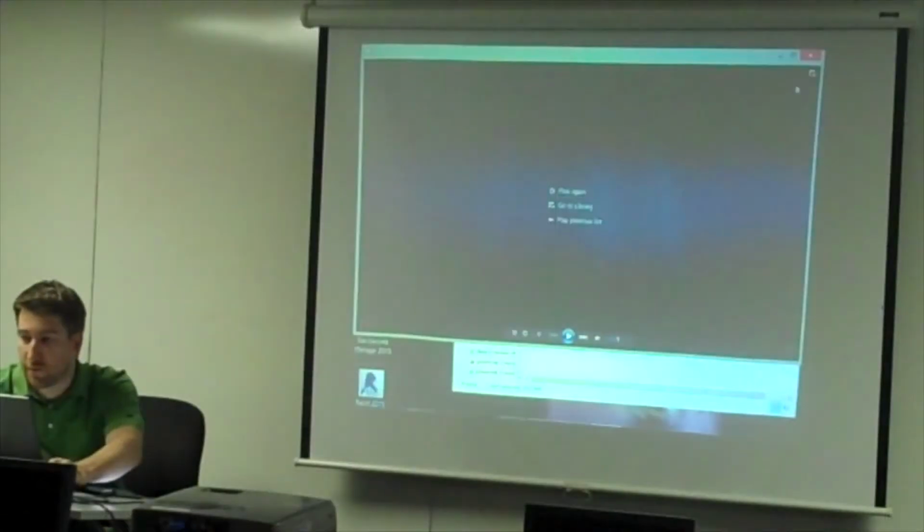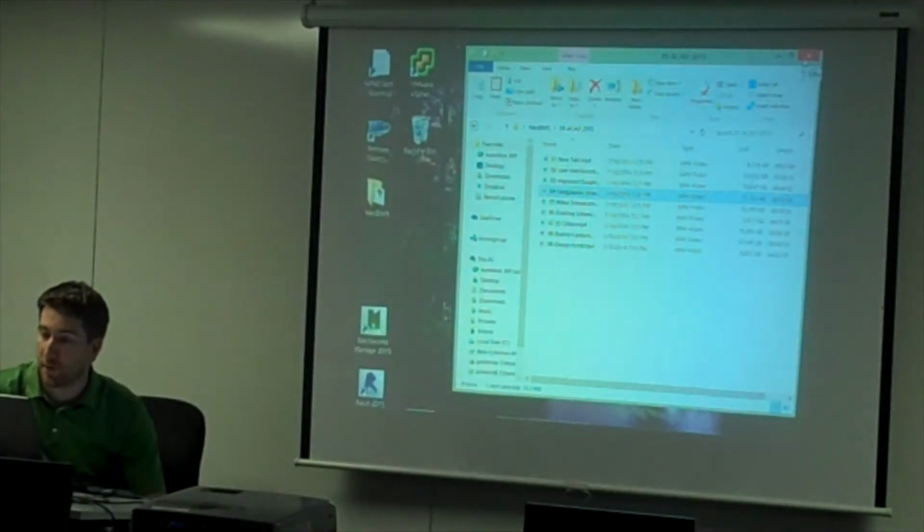So the part I like about this one, for people that deal with GIS information all the time, they're familiar with coordinate systems and how that stuff works, but if you're doing architecture, for example, and you're just trying to plot a building down on a site plan, it takes a lot of that out of the mix for you. It allows you to just basically have a location and a rotation to be able to set that thing orientated on its site and be able to leverage imagery and other things that you either have no access to or have a really difficult time modifying to fit your need when you use that kind of stuff.